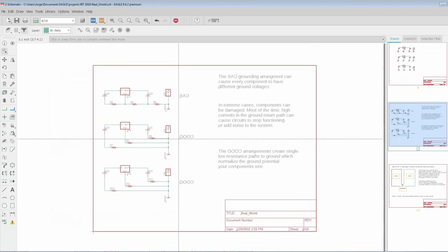First, we've determined how we can see if we have high-speed signals or not. Okay, the simple rule of thumb, if you have clock frequencies higher than 100 megahertz and or rise times shorter than about 1 nanosecond, you have a high-speed signal, and you need to start thinking about signal integrity very, very carefully. Okay? Impedance is the language of signal integrity.